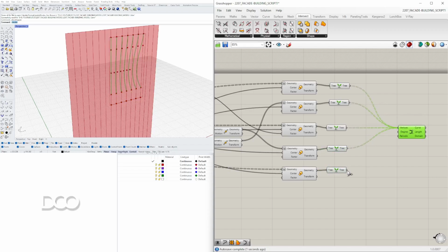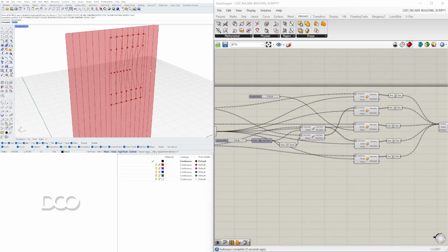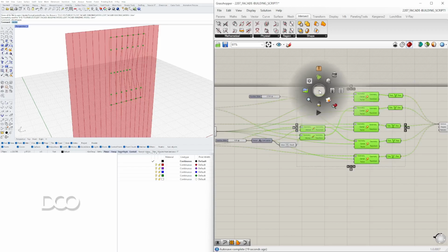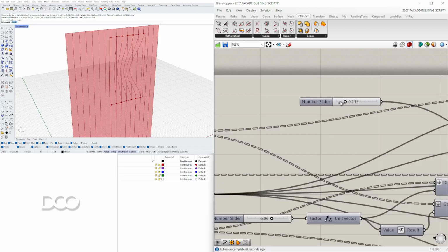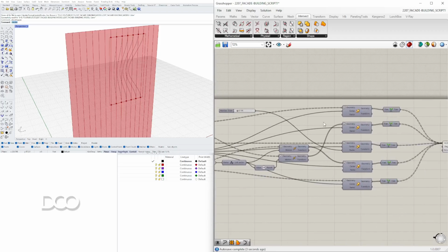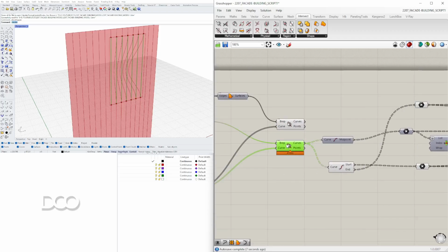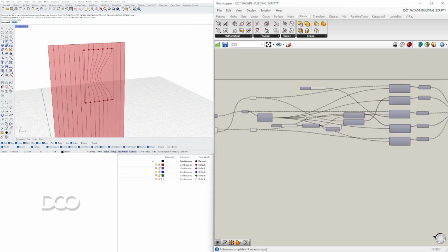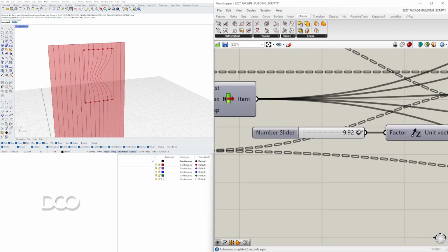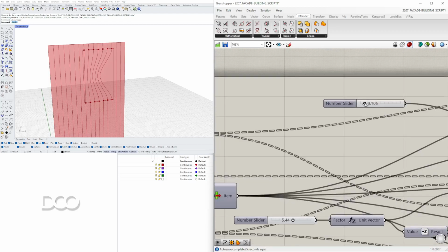We'll make a copy and then merge these together using graft and NURBS curve, right? So what did we do? We took outside point, the end points, move them up, top points, move them down, and then the midpoints and scale them to one side. Now we can take all of these points, disable preview, and then scale down here and remove, since that they're basically overlapping, is take those away, and now that takes care of it. And the reason why we did this one is because this will help us make it smoother or not.